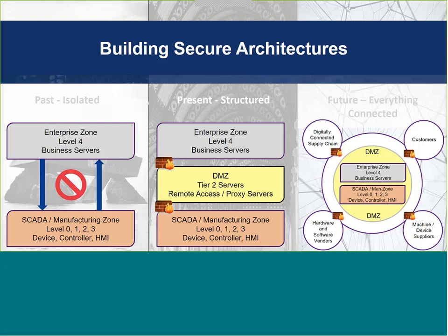But because everything is segregated, you've got no opportunity to connect your SCADA system to anything else, such as MES integration. And from a security perspective, you've still got the possibility that an operator could collect a USB stick out of a car park and infiltrate the network that way.